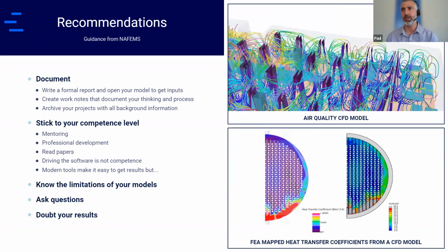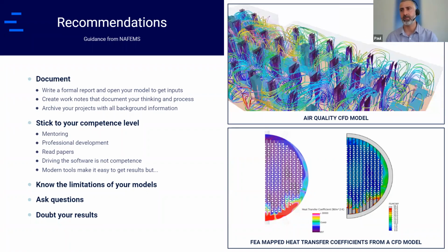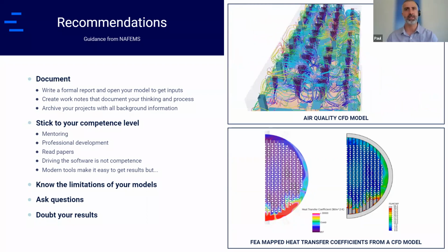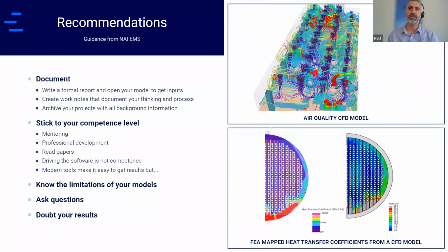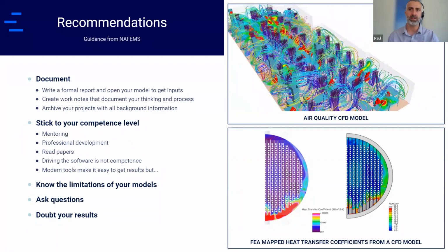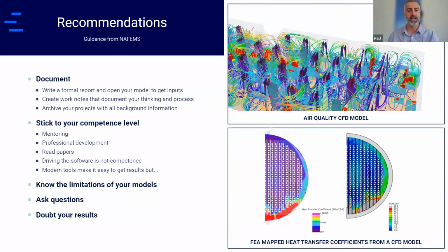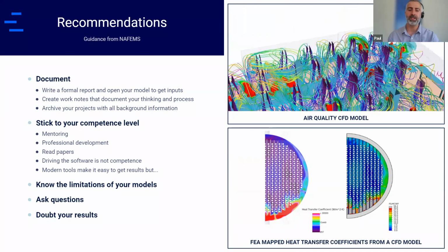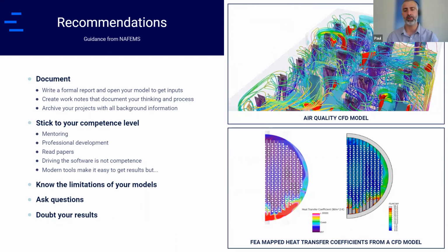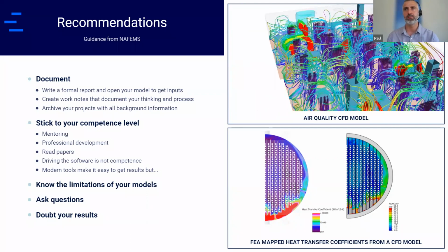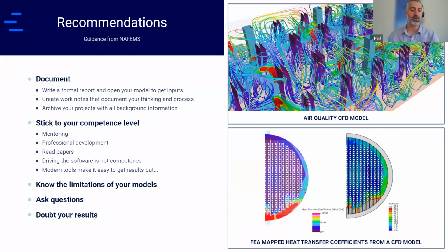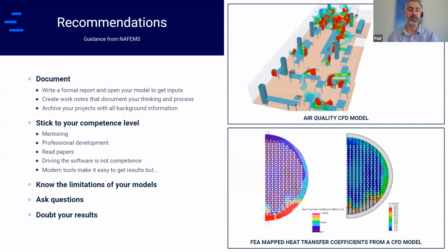When I started, I started with Patran and Abaqus, and it was really hard to get a mesh. Even to learn the software took months. These days you can get CAD embedded software, you can get a mesh and a pretty picture very, very quickly, but it's more difficult to understand the limitations, more difficult to understand how to interpret the results, and more difficult to build valid models than it is to actually drive the software. So software isn't competence.